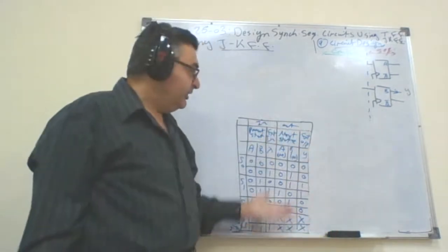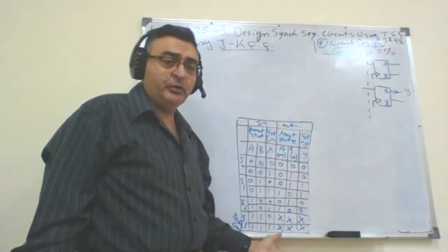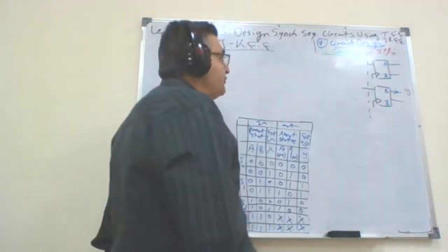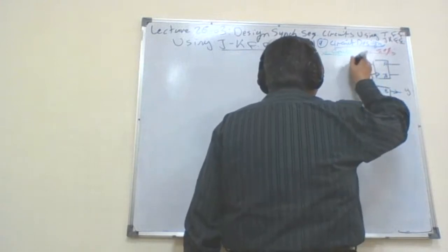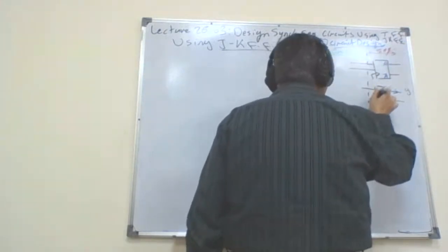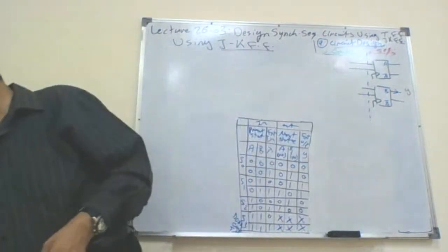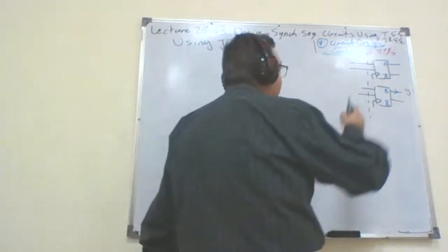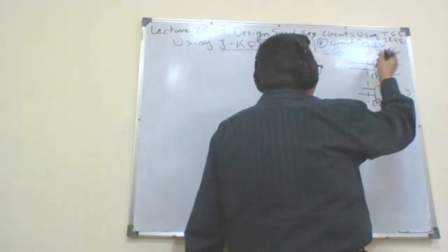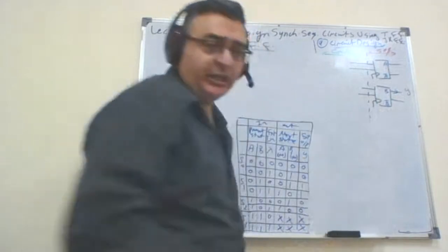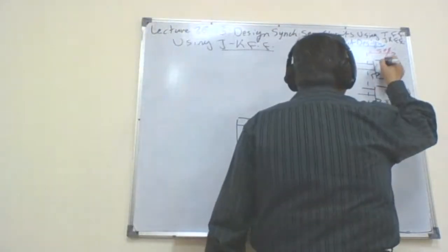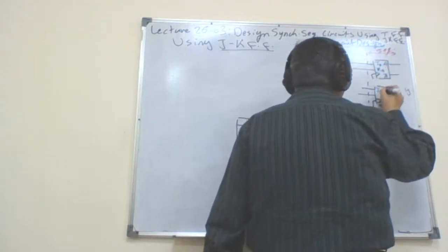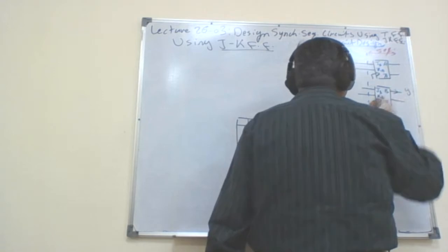Everything will remain the same. The state table that we already developed will remain the same. But right now, we want to go back and replace those flip-flops by JK flip-flops. So we have actually two intermediate inputs between the combinational and sequential. Since those flip-flops are JK flip-flops, I have what we call the JA and KA, and I have here JB and KB.